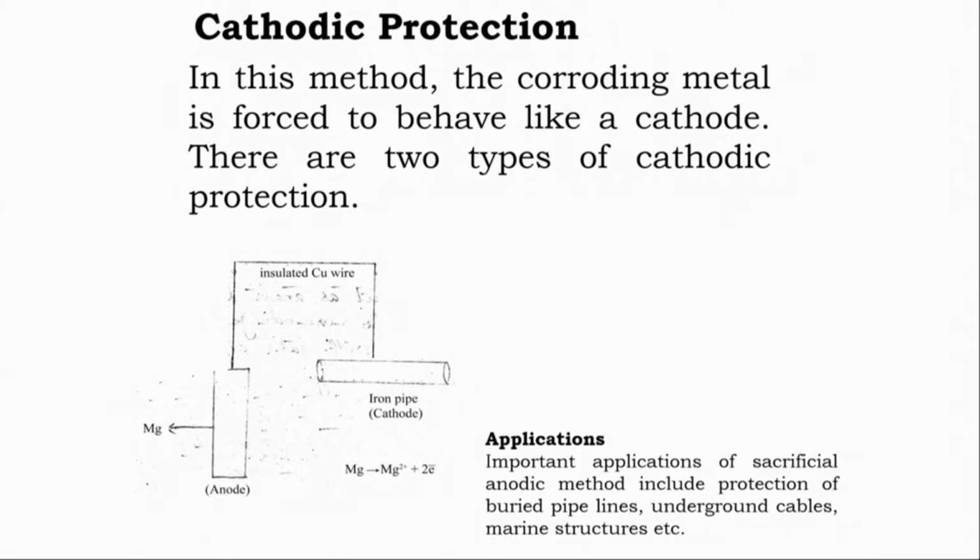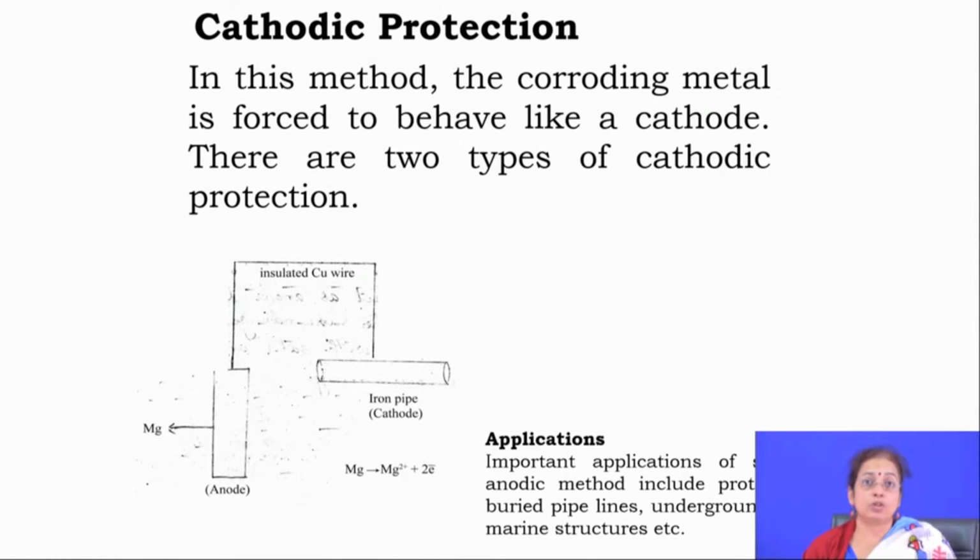Whenever the anode is subjected to corrosion, naturally there is evolution of a lot of electrons, and whenever that electron is evolved, your cathode is highly protected. So, your metal is highly protected, since it is acting as cathode. So, there is no corrosion at all. This is a very important way of protecting the metal from any kind of aqueous corrosion.